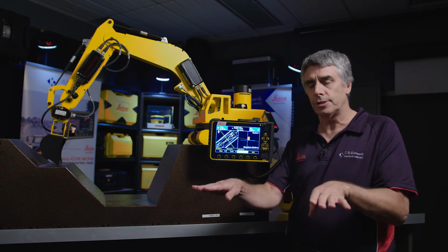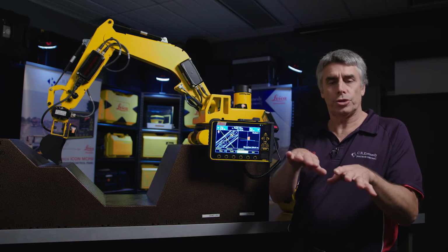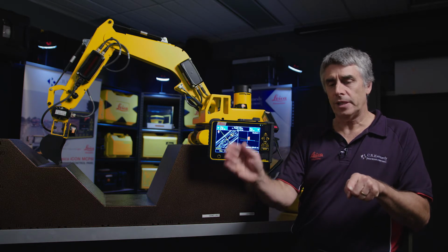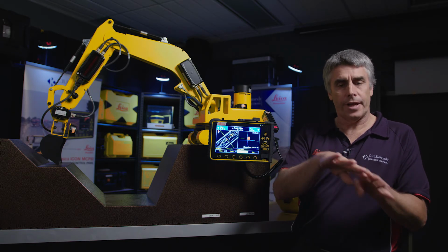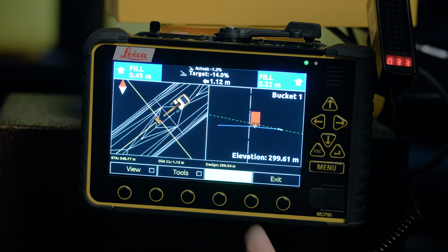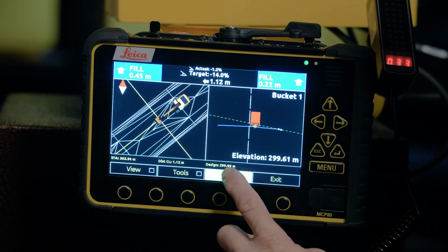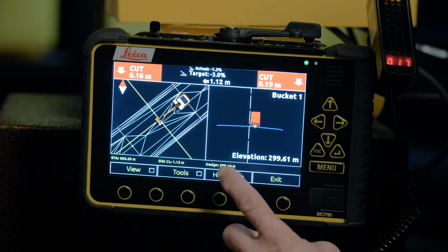So if it's a flat surface, it'll be flat. Where the road changes, because this is a road, to a shoulder, if you pick the offset from that centre line to the shoulder, that's what you'll get, and that's what we have displayed here. That hold slope will carry on for the duration of the surface. You can turn it on and off as much as you like, as per required. And that's how you hold slope from a centre line in Icon 3D software.